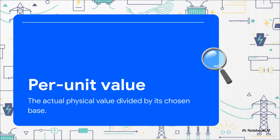Okay, so a per-unit value is really just the actual physical value divided by its chosen base. And since the units completely cancel out, the resulting number is dimensionless. But here's the catch. A bare number like 0.12 per unit is utterly meaningless unless we know its exact quantity, its base set, its phase convention, and its network region. Basically, it desperately needs metadata to make any sense.